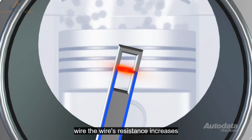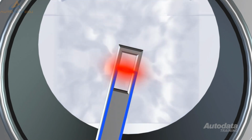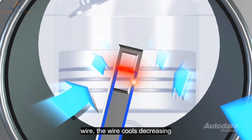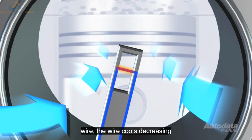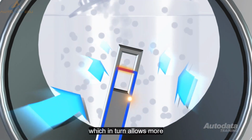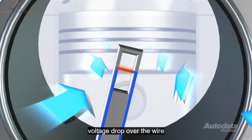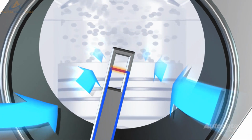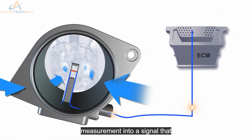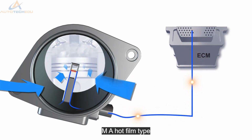The wire's resistance increases as the temperature increases. When air flows past, the wire cools, decreasing its resistance, which in turn allows more current to flow through the circuit or causes a smaller voltage drop over the wire. The sensor converts the measurement into a signal that is sent to the ECM.